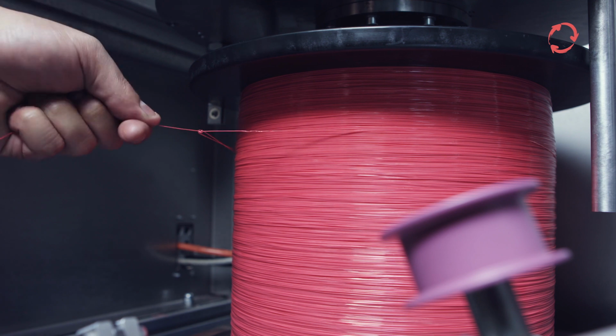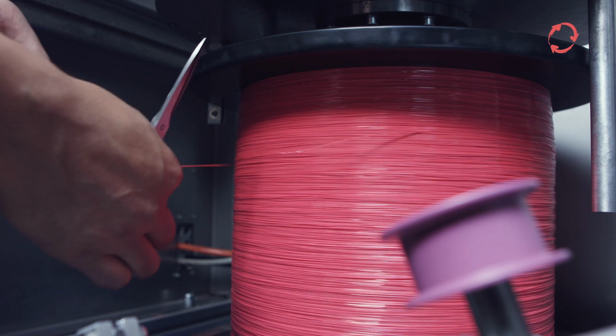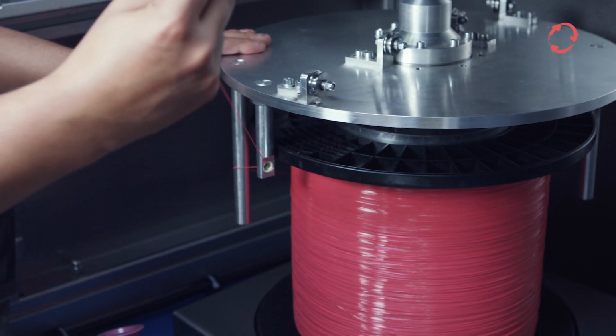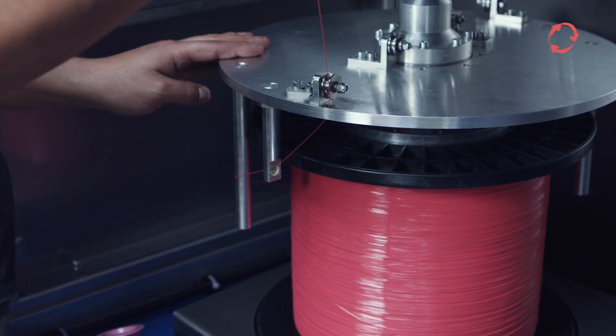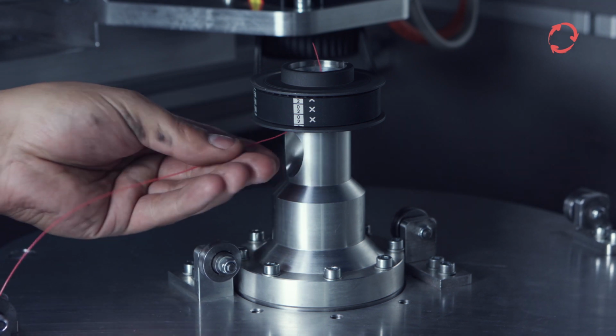Use scissors to cut the knot of the thread on the coil. Pass the thread past the first guide pin and through the second pin. Now pull the thread through the guide hole of the winding plate to the top. The further course goes through the first guide roller on the winding plate to the passage opening in the hub